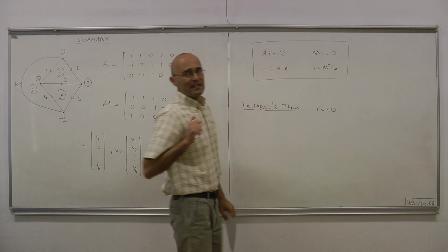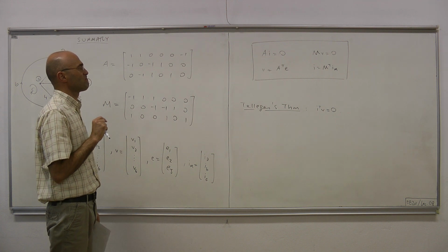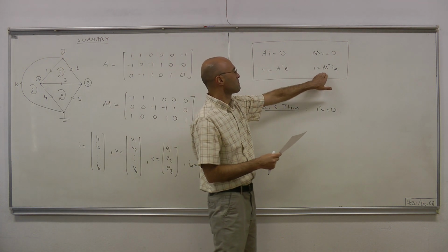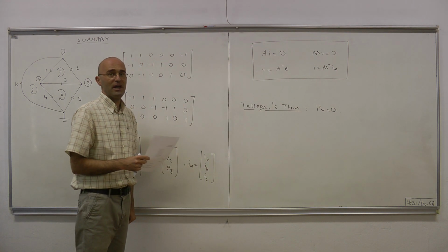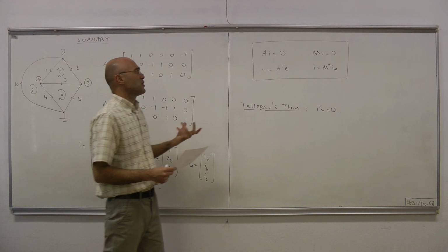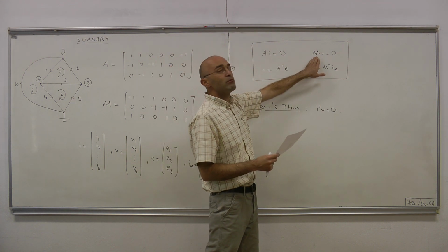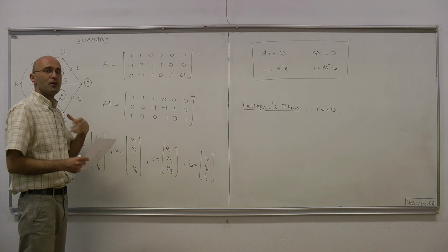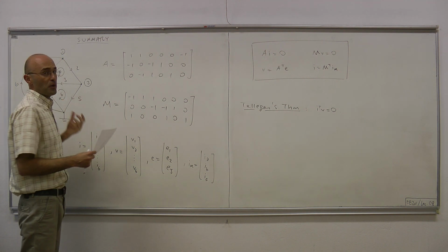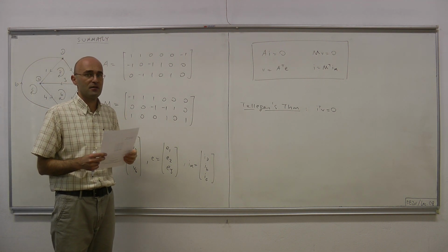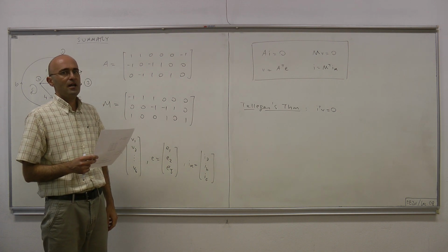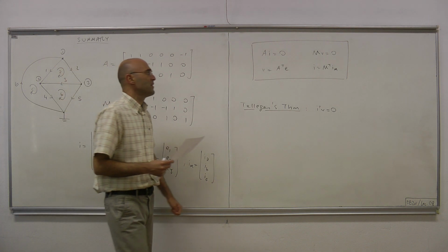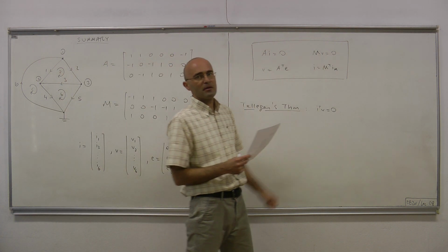Now, there's one little disadvantage to this formulation, and that disadvantage is that in order to be able to talk about inner meshes, your circuit must be a planar circuit, okay, or a planar graph. But there are certainly circuits that are not planar, and in that case, this method is not directly applicable.